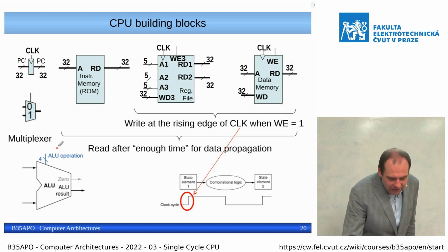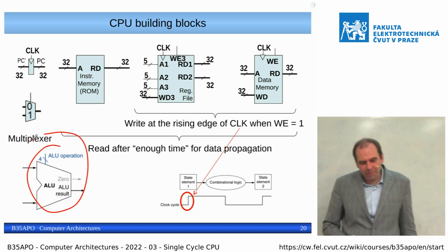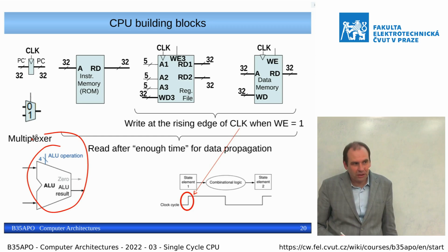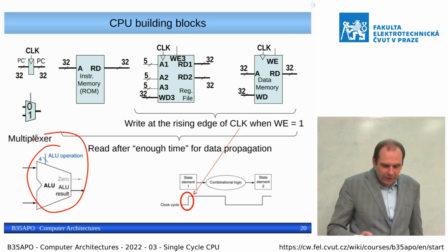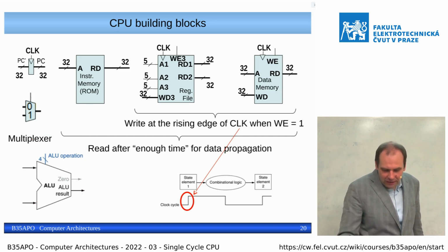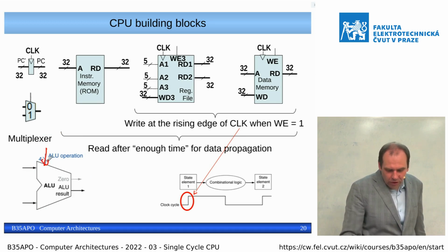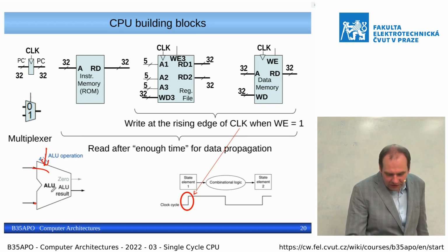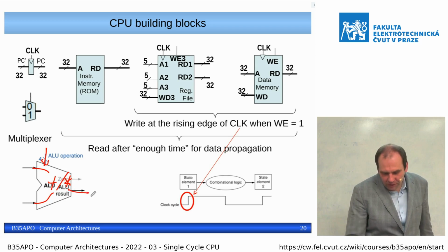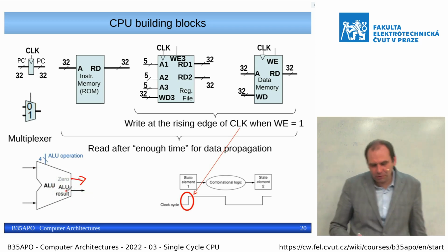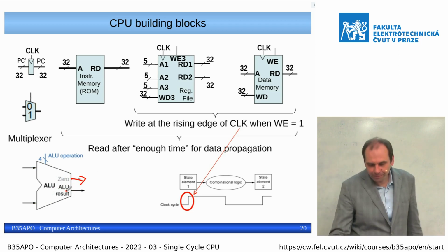And then we have this, in fact, most complex block, which is the arithmetic logic unit. There are others, multiplications, shift and so on. But for our design, we can look at it as a black box, which we only control by what operation should be processed, if it should be plus or divide or multiplication between 2 inputs. And on the output we have a 32-bit result and some indication if the result is 0 or not, for example, or something more.